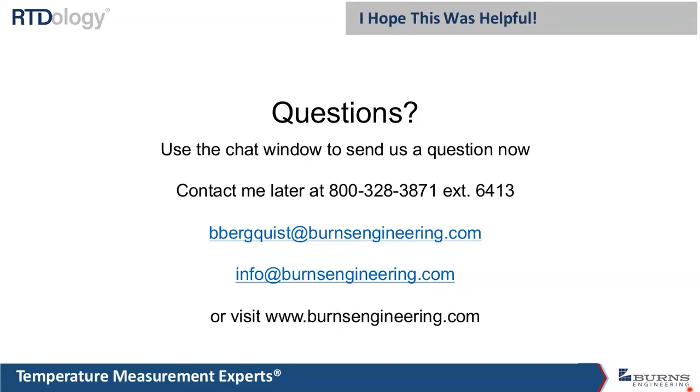The benefits of that: one, it's size. It's a smaller footprint. Another benefit is it can't be hooked up incorrectly. The connectors only go on one way. And it's easy to remove it and reinstall it if you're going to either replace the sensor or calibrate the sensor. So we do see it more and more, mostly in biotech, where they're on some type of skid and there's just not a lot of room to have the larger head. It is another connection point, but Bill, any comments on that?